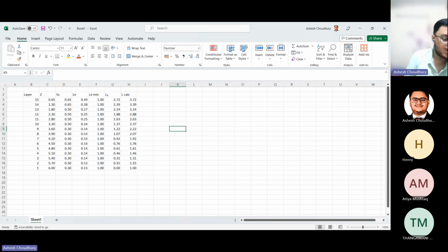Now up to some height we can provide one length, and up to another height we can provide another length. So we can subdivide. Providing different length for each layer is difficult, because you need to measure and cut the reinforcement in such a way for each layer. So we divide the complete wall in some blocks, and we fix the length for each block.